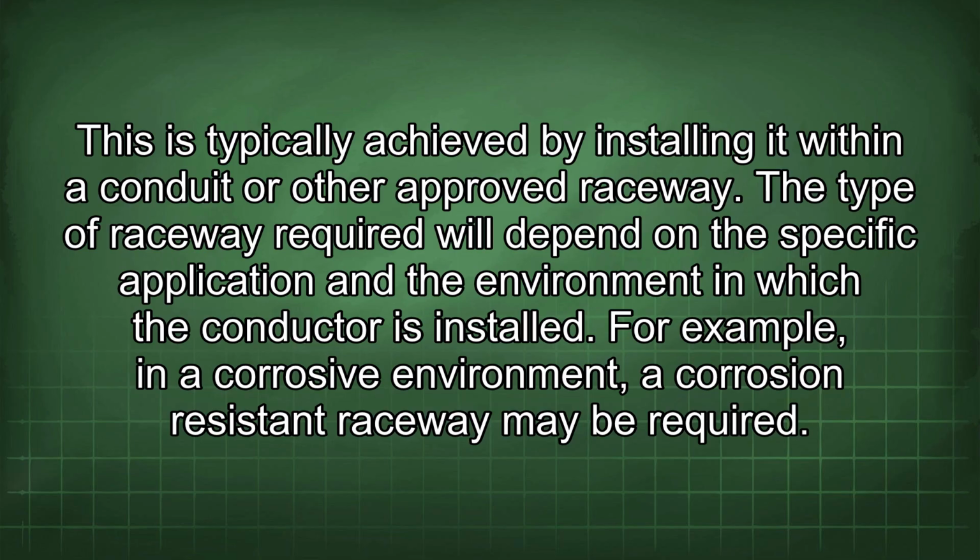This is typically achieved by installing it within a conduit or other approved raceway. The type of raceway required will depend on the specific application and the environment in which the conductor is installed. For example, in a corrosive environment, a corrosion-resistant raceway may be required.